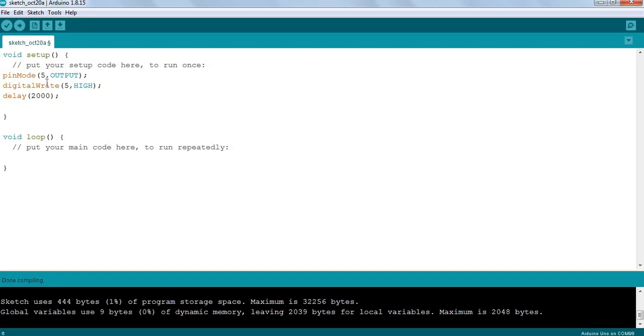Switching off the LED means we don't want any current to be flowing through the LED, and for that we'll stop giving voltage to the LED. That means we will make the polarities of both the LED pins the same. When the polarities are the same, there is no current flowing. That means we will have to apply a LOW value to the anode pin.